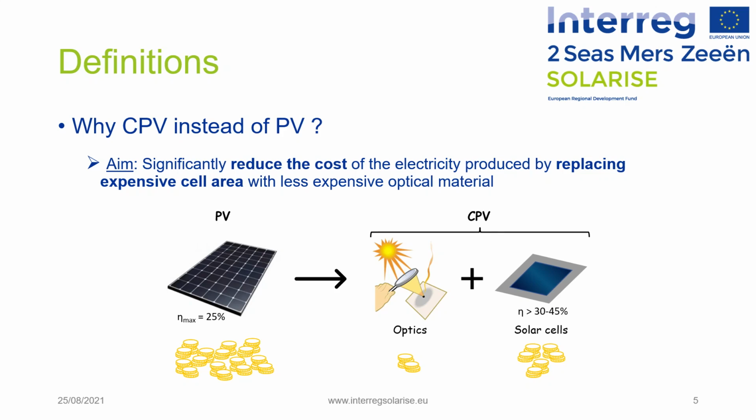As a result, CPV modules can easily exceed 30% energy conversion efficiency. They are even expected to exceed 50% in the medium term, when the common PV technology has a maximum efficiency of about 25%. Therefore, CPV technology can be seen as an innovating and enhanced version of usual photovoltaics that would produce more electrical power output at lower cost.